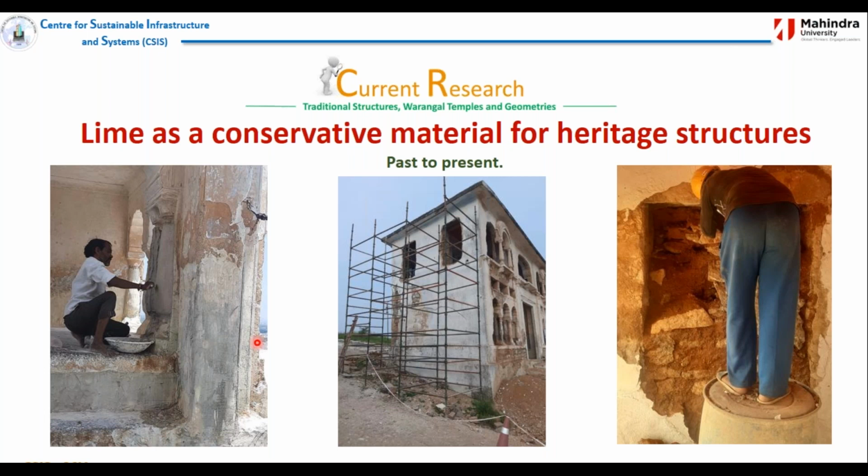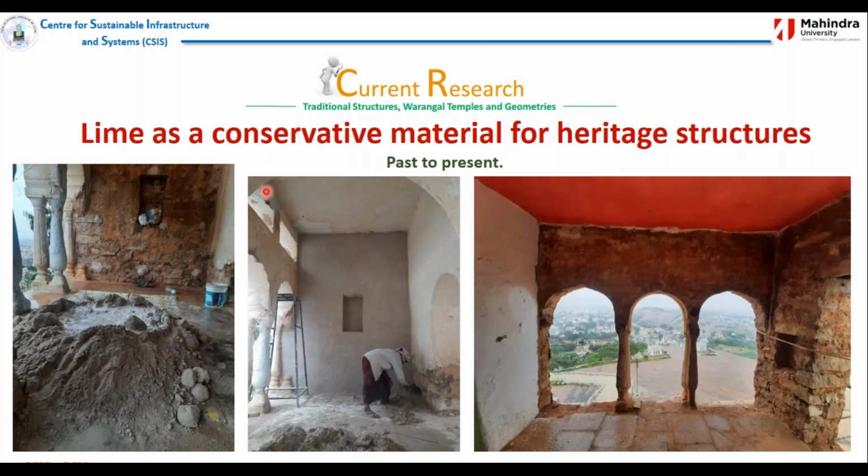Now, if there is a procedure to finish and get the old layer, at certain places we have to go even for 75 mm. For 75 mm, we were getting shrinkage cracks. So we cannot have more than 15 mm at the same point of time. So we have to go 15 mm, 15 mm, 15 mm.